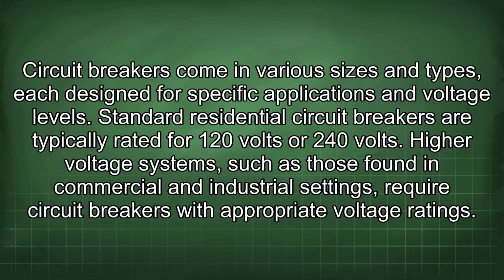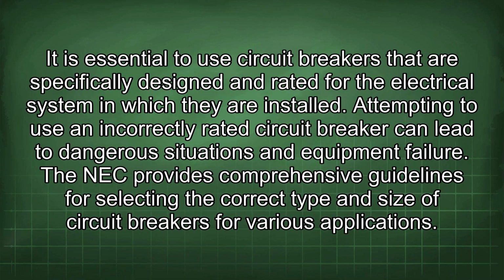Circuit breakers come in various sizes and types, each designed for specific applications and voltage levels. Standard residential circuit breakers are typically rated for 120 volts or 240 volts. Higher voltage systems, such as those found in commercial and industrial settings, require circuit breakers with appropriate voltage ratings. It is essential to use circuit breakers that are specifically designed and rated for the electrical system in which they are installed. Attempting to use an incorrectly rated circuit breaker can lead to dangerous situations and equipment failure.